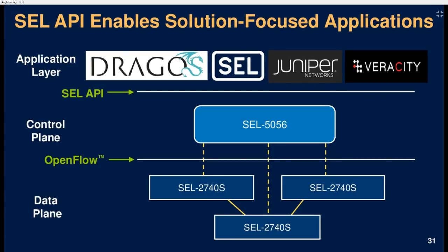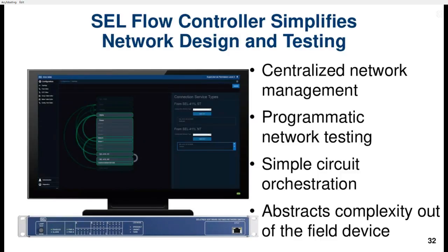To sum this up, the SCM really does a strong job of centralizing network management and programmatic network testing. When a link fails, we know the secondary path. We know the length of that secondary path, which we can then give deterministically to the protection engineers so they can calculate that the secondary path is going to take this long as opposed to the primary path.